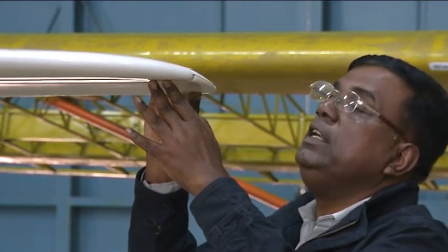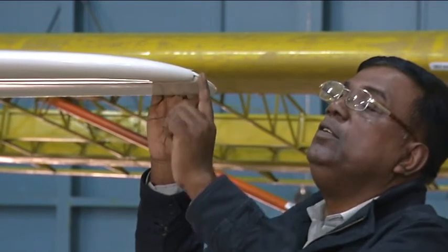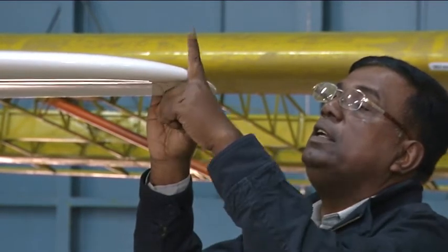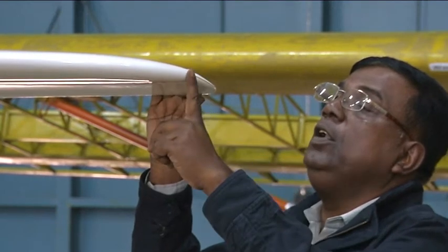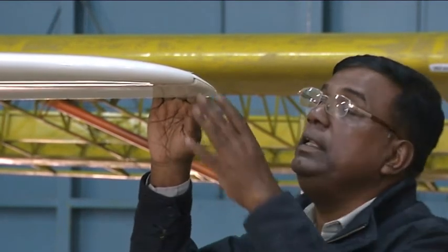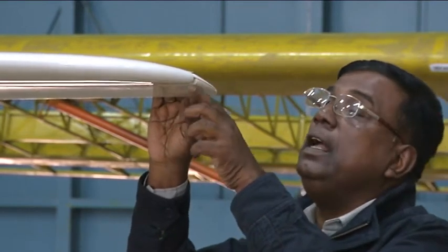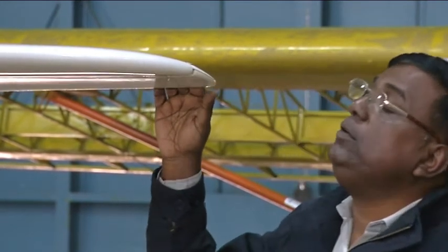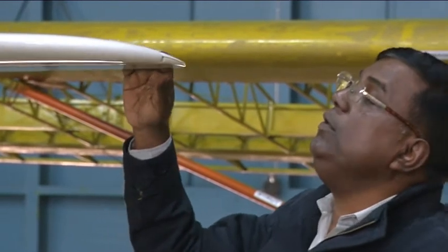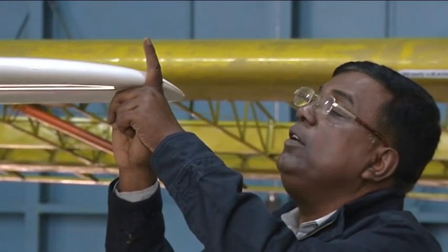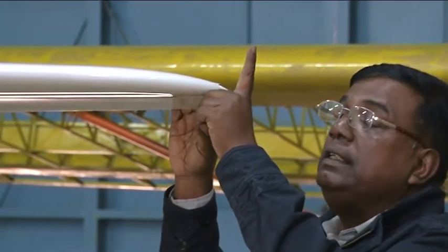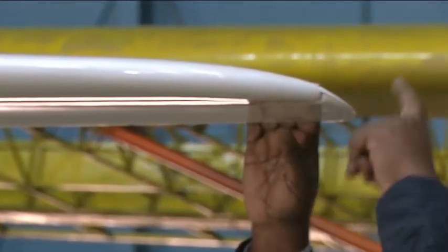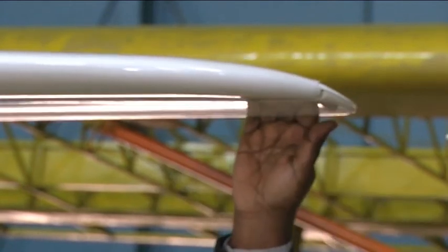But when I put the elevator down, even for alpha equal to 0, there will be a vertical force. In non-dimensional form, we call it delta CLT. And why is that happening? That is happening because there is elevator deflection. One way to explain it is that the zero lift line has now changed. But when we talk about CL delta E, what we are looking for is how much delta CL is increased because of elevator deflection. And how much that CL delta E contributes towards the moment about the center of gravity is CM delta E. So these two control derivatives are extremely important for longitudinal control.